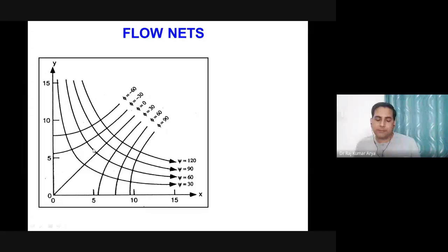These are the zones where the velocity magnitude has decreased between the two streamlines due to change of direction. The flow rate between two streamlines needs to be conserved, so you cover more area so that more fluid can be taken out. That is the continuity part here, so they need to satisfy continuity.